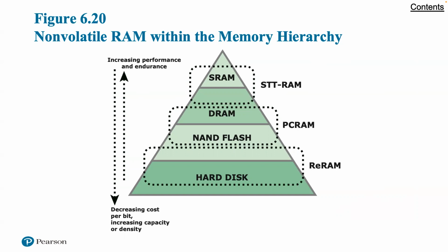Next, we have hard disks. A magnetic disk provides very high bit density and very low cost per bit with relatively slow access times, and it is traditionally the choice for external storage. Storage is part of a memory hierarchy. Into the mix, as we have seen, has been added flash memory. Flash memory has the advantage over traditional memory that it is non-volatile. NOR flash is best suited to storing programs and static application data in embedded systems, while NAND flash has characteristics intermediate between DRAM and hard disks.